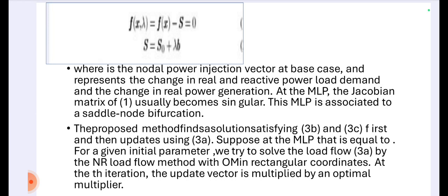This MLP is associated with saddle node bifurcation. The proposed method finds a solution satisfying the load flow equations first and then updates lambda.